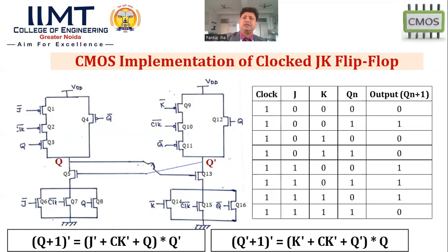Further, since latch has the synchronization issue of output, we moved towards flip-flop. We have implemented SR flip-flop and JK flip-flop. The basic difference between latch and flip-flop is that in flip-flop, there is a clock circuit which synchronizes our output. Means when the next output is going to change will be decided by the clock itself.